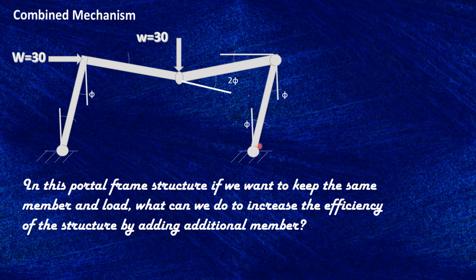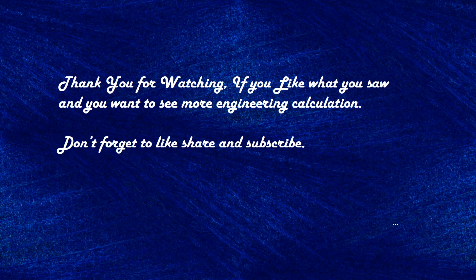Of course, in addition to that, we can upgrade the members, providing bigger size or bigger moment capacity structures, or then again maybe reduce the load, which is not actually what you want as a structural engineer, you want to keep the load. So maybe change the members, provide bracings, strengthen the joints, all sorts of things that can be proposed for these structures. So this is how we can do a portal frame analysis.